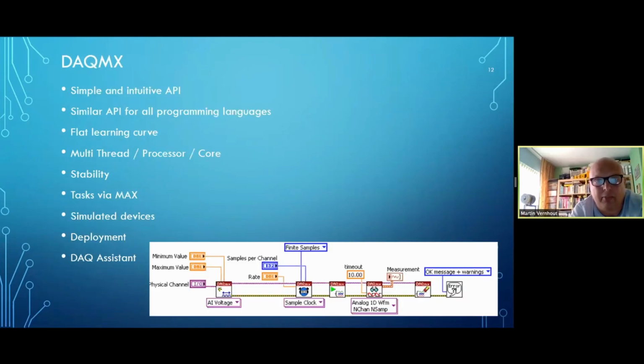All right, DAQmx. If you've not used DAQmx before, you probably haven't used a data acquisition device from National Instruments. So the moment you start using a multifunction I/O device or some analog input module, you are going to use DAQmx or the traditional DAQ driver. It's a simple and intuitive API. It has a flat learning curve, and there are tons and tons of examples out there on how to do the things you want to do.